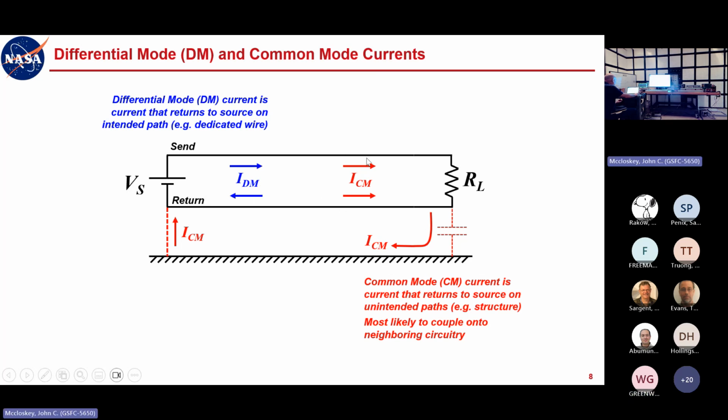But the common mode is the net current that is not coming back on the intentional return path and is finding some other path back to the source. And if it's finding some other path that is not conductive, if it's not some actual conductor, then it's some other impedance that is most likely capacitive. That is the only other option. And I know that there is capacitance between these conductors and the ground plane, and I've shown you in other sessions how to calculate that. So when you say there's no capacitance between the conductors and the ground plane, I don't understand that statement at all.